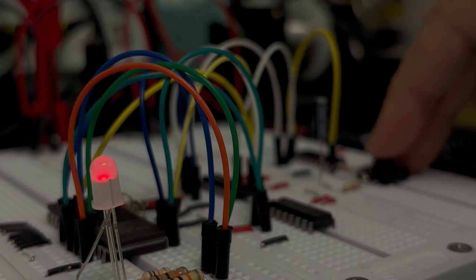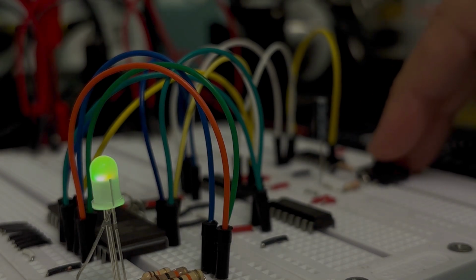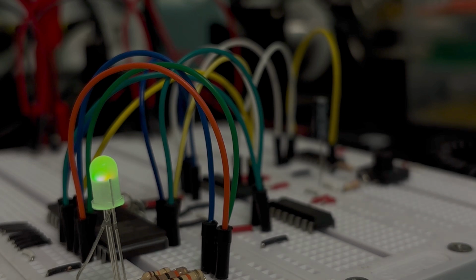The footprint is likely much smaller than it would have been had I derived individual minimized expressions for each next state and output variable. In fact, I had the idea to program this on an EPROM after looking at minimized expressions that I derived for the circuit and deciding they'd be too annoying to implement with AND, OR, and NOT gates.